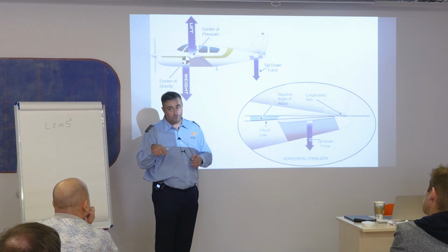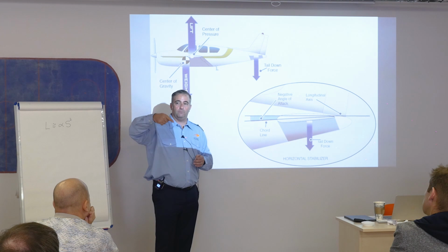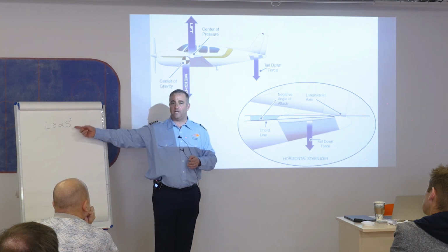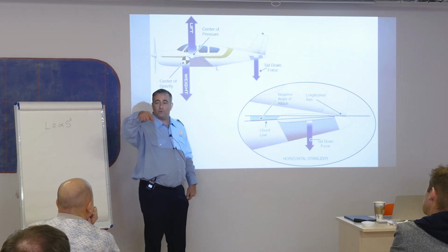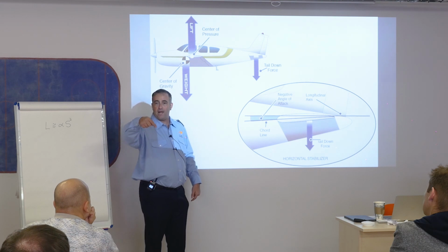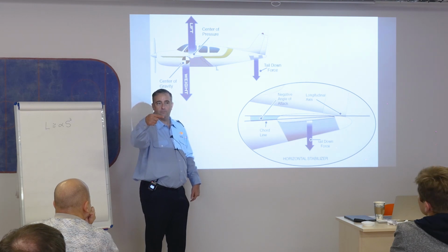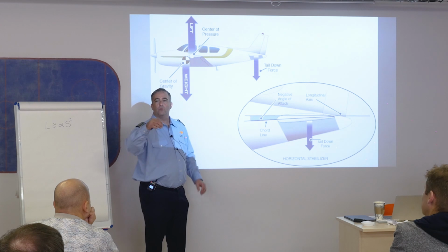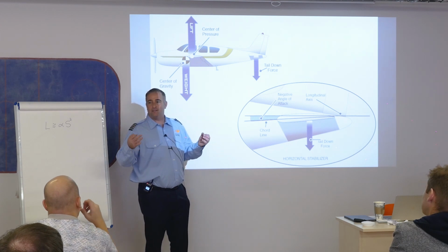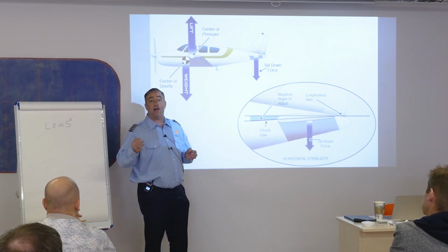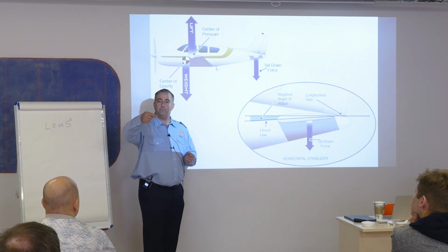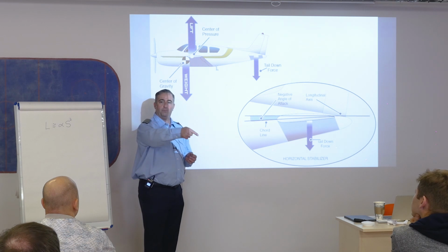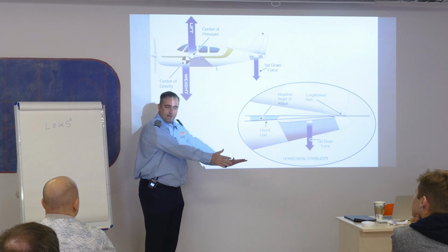It'll increase speed. So now I've got an airplane that was pointing downwards, and it's increasing speed. I get more speed, so that means I get more tail force. What happens with the nose? It goes back up. Okay? So this begins the process of positive dynamic stability, which means after a period of time, the airplane will fly in a straight path down.